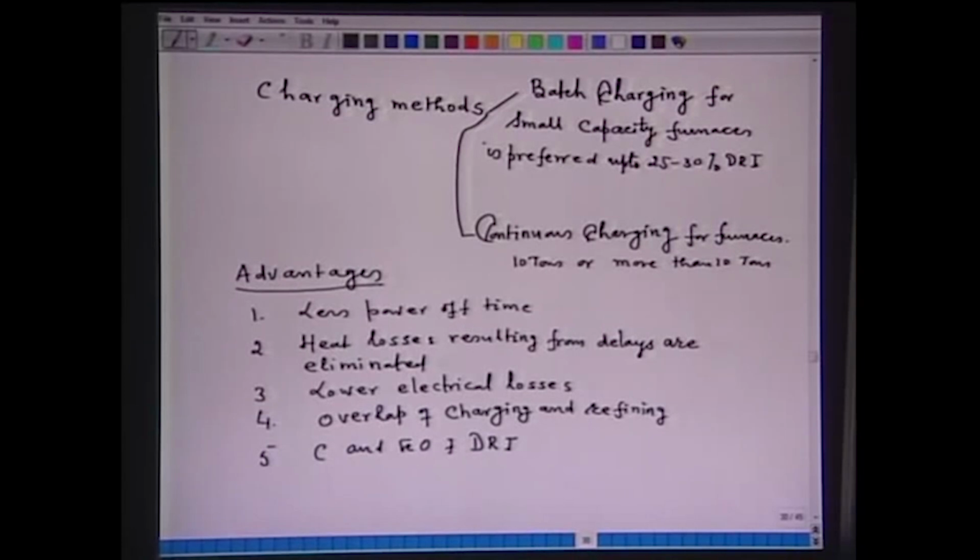As a result, this reaction produces heat. This reaction produces a strong carbon boil during charging. Now, remember, this reaction between C and FeO takes place during charging, and the CO which results creates a strong bath agitation in the bath.